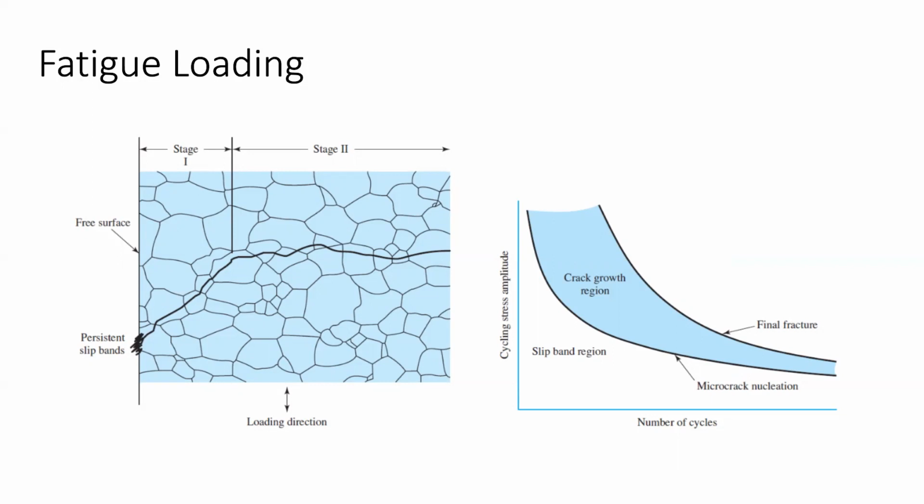As the wheel actually rotates relative to the hub, which is spinning, that moment load is actually rotating around the hub. This isn't super obvious because you don't typically think of loading in the frame of a rotating part, but because this hub is rotating, even though the normal load, relative to our inertial frame of reference, is stationary on the wheel, it's actually rotating on the hub. So they didn't recognize that. And what happened? It fatigued that joint.